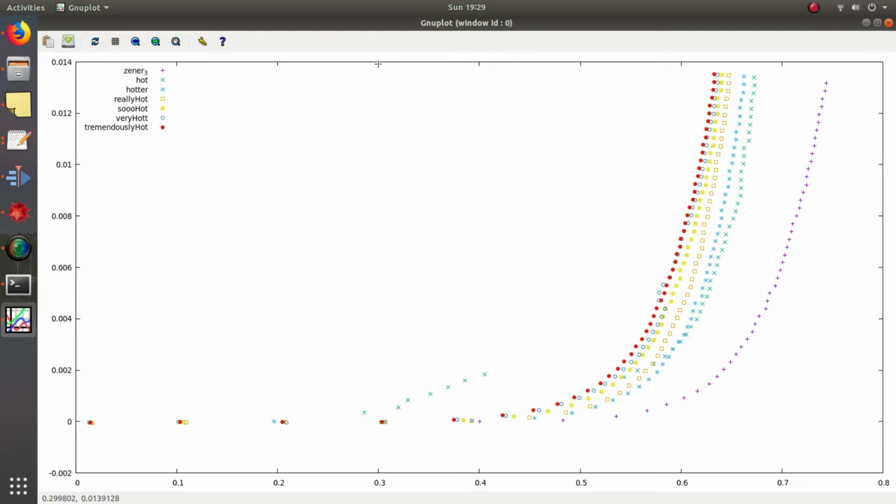And so I think there's something else happening, some other temperature dependence, and from a quick read, this makes sense from my semiconductor classes. This is shifting because by increasing the temperature, I'm actually increasing the Fermi level of one end of the junction, the electrons or holes at one end of the junction, essentially decreasing the amount of energy that I need to put in to get current to flow through these guys, and it's also increasing the carrier concentration in the semiconductor. So I'm going to have to review this and probably make a better explanation.